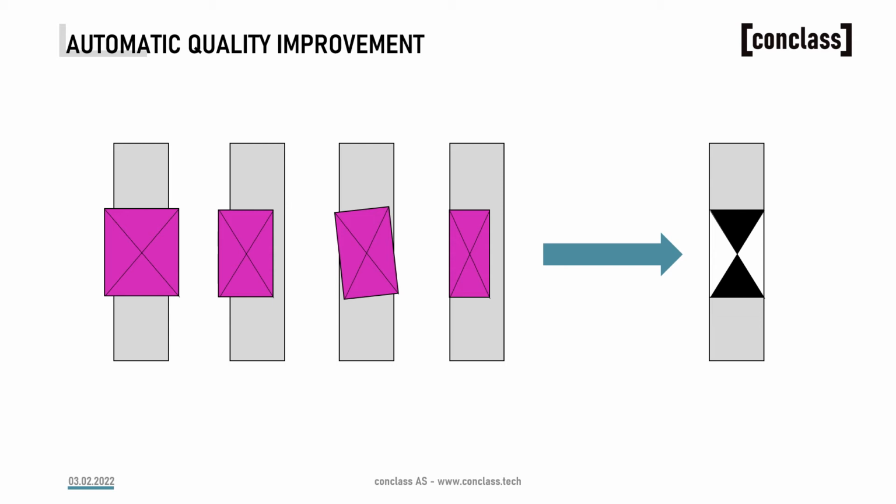The example to the left is a really common problem in structural models. If the MEP engineer created the opening based on an architectural and a structural model, there are often non-structural walls attached to a structural wall. Since the structural model does not have the non-structural walls, the thickness of the opening has to be adjusted. ConVoid will solve these inaccuracies automatically to make sure you will get the correct dimension and location as supposed to be.